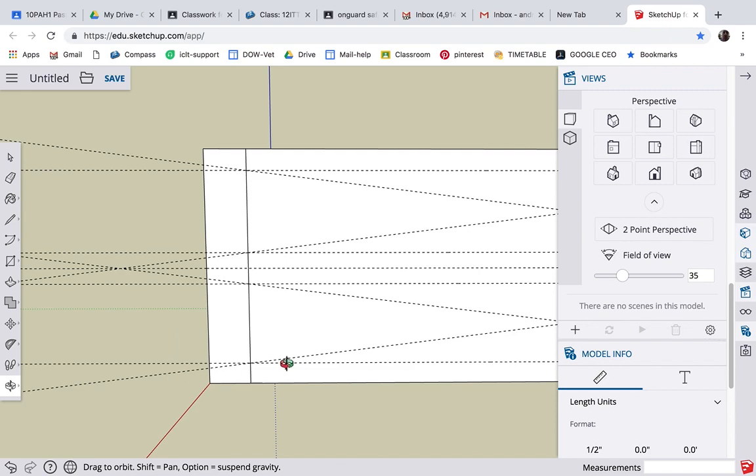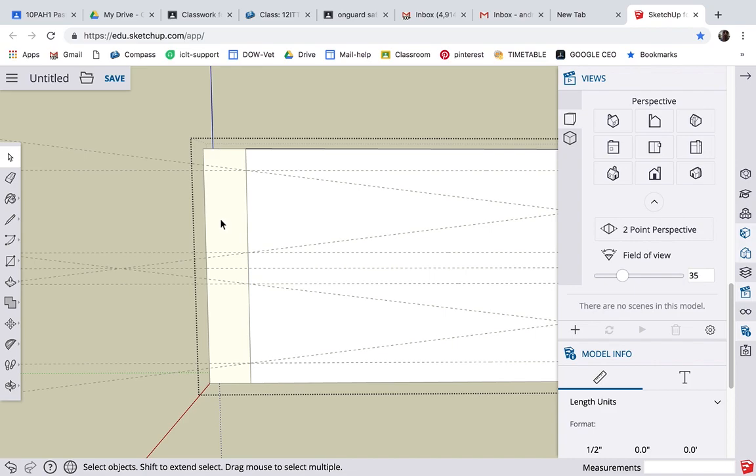Now, all that's left for us to do is to actually draw the dovetails. The dovetails are drawn on this long object here. So we open that in edit mode, and we're going to use the line tool, which is L, and we're going to trace from there to there to there. Escape. We trace from there, click, click, click, click, escape, and then click, click, click. Now you'll notice I've gone through from outside to outside, outside through to outside, outside through to outside.